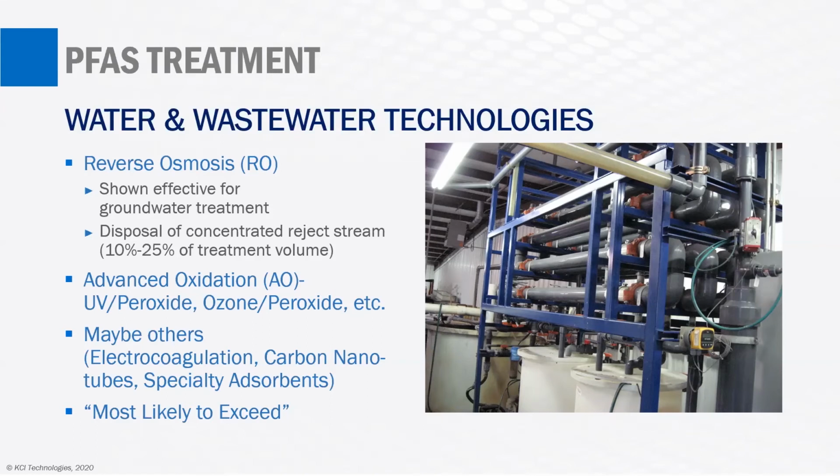So as we move down this list here, we're moving into more advanced and less developed technologies. Advanced oxidation has been used effectively, for example, on water utilities for taste and odor removal. And so in that sense, it's not a new technology, but when we're applying it to PFAS, its effectiveness on the various components and so forth is still not really known. And so it's not developed for a large scale use with respect to PFAS.